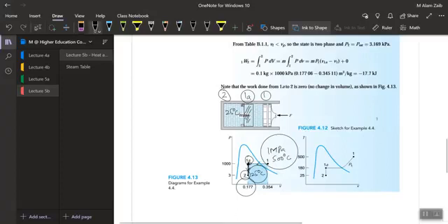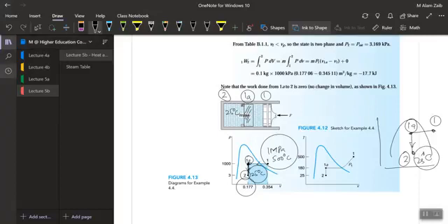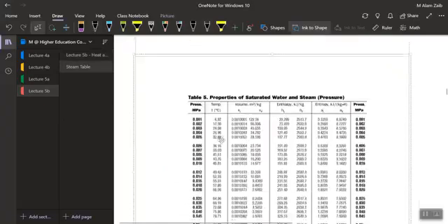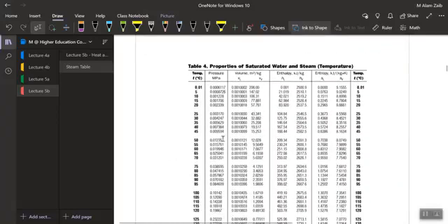What I mean to say is, as my volume V2, sorry for that, as my state 1A is in a saturated region, keeping the volume constant and decreasing the pressure, we would still be in a saturated region. So at state 2, 25 degrees centigrade, I am still in a saturated region, that means in a mixed region. So going back to the temperature table at 25 degrees centigrade, I have got a pressure of 0.003170, which is equal to 3.170 kilopascal.